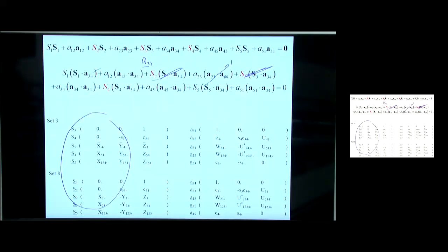And what I would wind up with is an equation that had that as the only unknown. And I would put in the A case angles and evaluate all the terms and get S4 for the A case, and then do the same with the B. And then lastly, we're missing one term, the S3 distance. And I'd probably do a dot product of everybody with S3. Just because that would go to 1, S3 dot itself. I've already got the A and the B case of those.